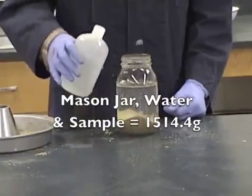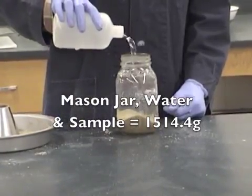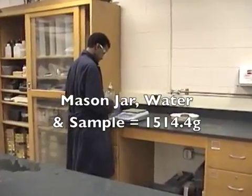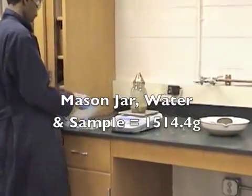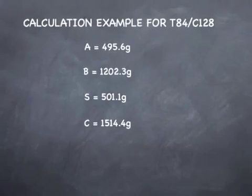And finally, C. This is the weight of the SSD specimen in the mason jar with the water filled to the calibration mark. For our example, let's assume that weight is 1,514.4 grams. And here are those weights listed individually.